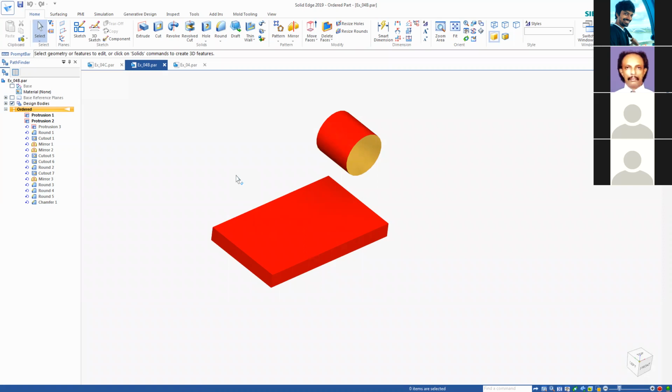flexibility level required. So if I want to control the individual fillets, then you have 4 different fillets. If you want to control them as one feature, independent of the base, then I can have one fillet feature, then select all 4 edges. So likewise, you decide the level of flexibility that you are expecting.